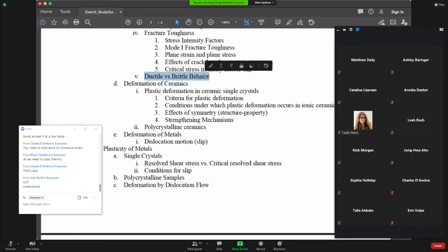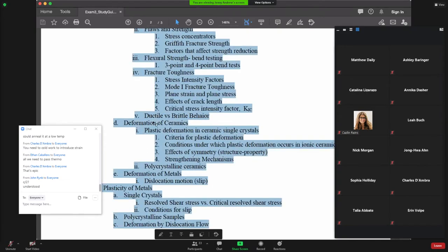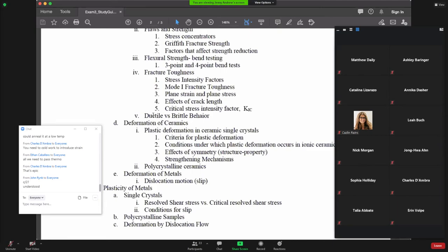We talked about ductile versus brittle behavior. And then, jumping back, toughness is really a measure of the energy a material can absorb prior to failure. So ductile materials can absorb a lot of energy, and that energy goes into the movement of dislocations. Brittle materials, they don't have dislocations that can move. So we were able to look at even some metals, and we had that, that's misspelled there, sorry about that. We looked at the fracture toughness, or the impact testing plot, and then looking at, well, when would we determine or decide that something was brittle or ductile?